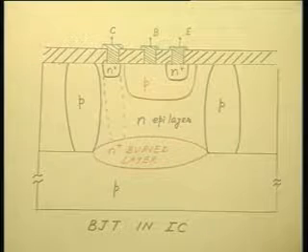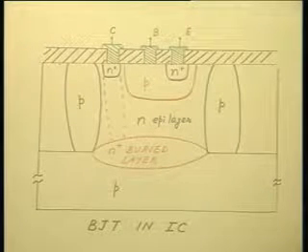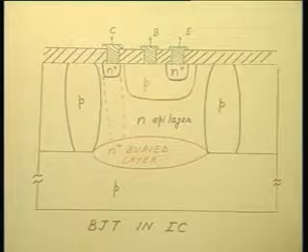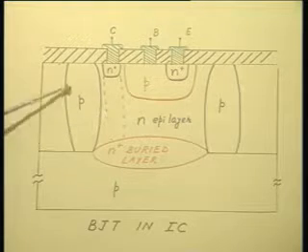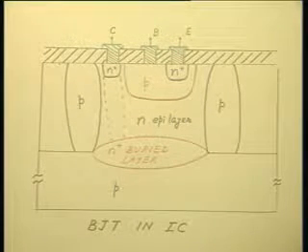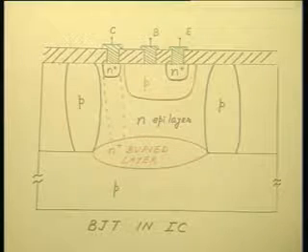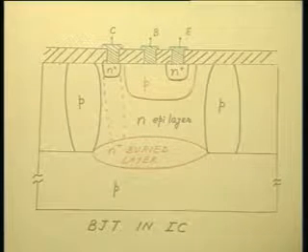Okay. So, this is, as I said, a comparatively older bipolar junction transistor which uses junction isolation, that is, this reverse biased PN junction is used as the method of isolation. Okay. Now, let us look at this junction isolation technology, because immediately after the buried layer we must concern ourselves with the junction isolation. Now, you see I am still talking about the older day technology.